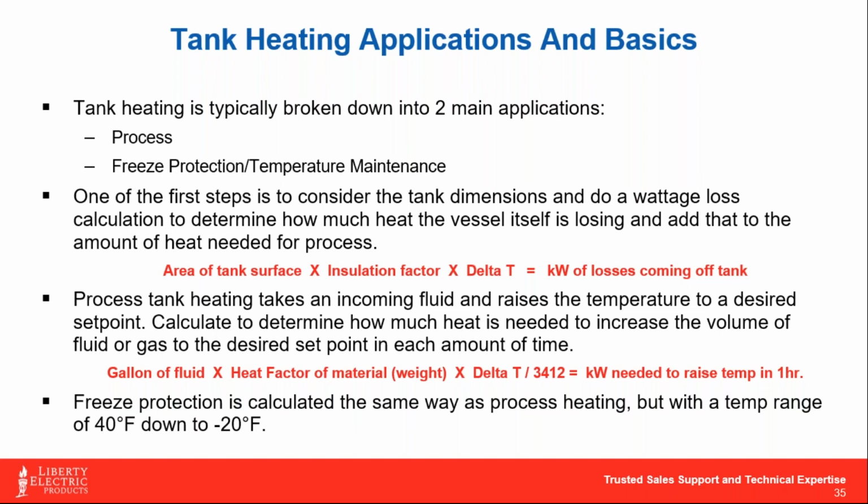a heat loss calculation, because obviously the bigger that tank is, the more heat the skin of it's going to emit. So we have to compensate for that before we can start really changing the temperature of anything that's inside of it. But in changing that temperature, there's a couple ways that we can look at it. There's either, I need that fluid to come up to temperature at a very fast rate. If I need 5,000 gallons heated up in 1 hour's time, it's going to be a much larger heater involved